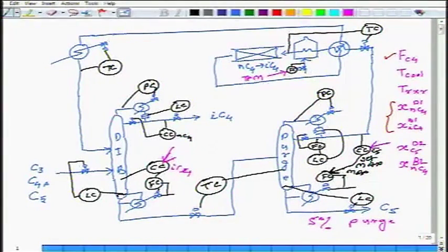Minimize the amount of IC4 leaking down the bottoms. Right? Keep on increasing it, keep on decreasing it, and then what will happen is the boil up will keep on going up until it hits its max limit. And once it hits its max limit, that's it. So here I have had to shift my throughput manipulator from the first active constraint to the next constraint to become active, to the next constraint to become active. There is this level of complexity that is there.